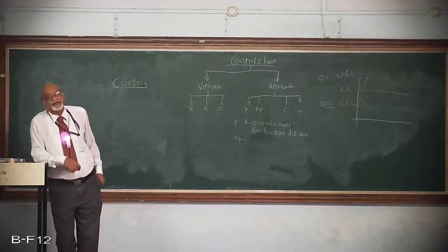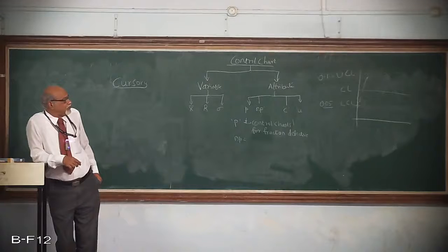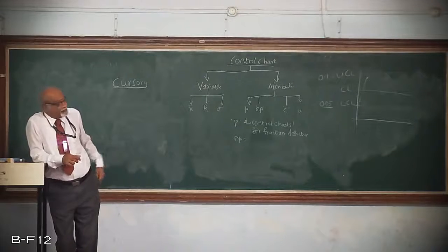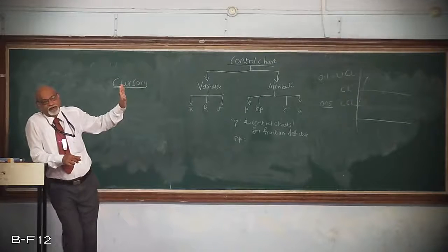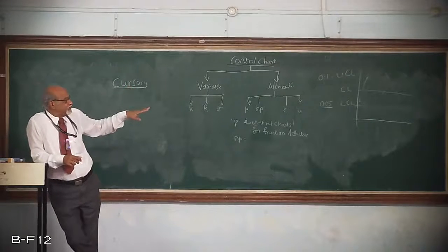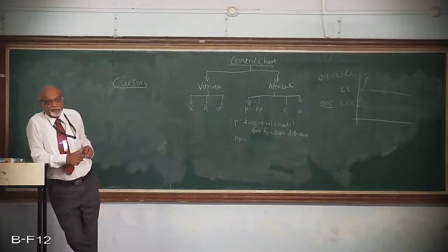So we will take a sample of 100, let us say. If it contains the number, because this is fraction defective, both are same. Upper control limit is 0.1 and lower control limit is 0.05. But again, the hinged point is the number of defective, because it has got a fraction defective of 0.1 and fraction defective of lower control limit as 0.05.